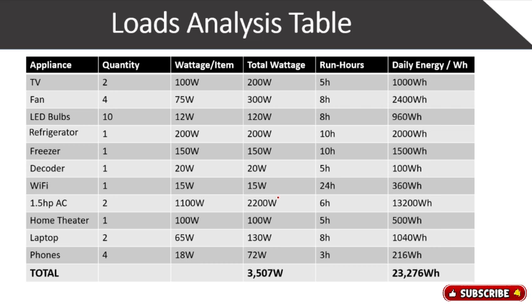And then you just went ahead and design your system and you install it. After you install it, you discover that the battery is draining faster. You now begin to wonder what is draining this battery. The problem is maybe you overlook these bulbs because you think these LED bulbs are just 12 watts. You overlook them.